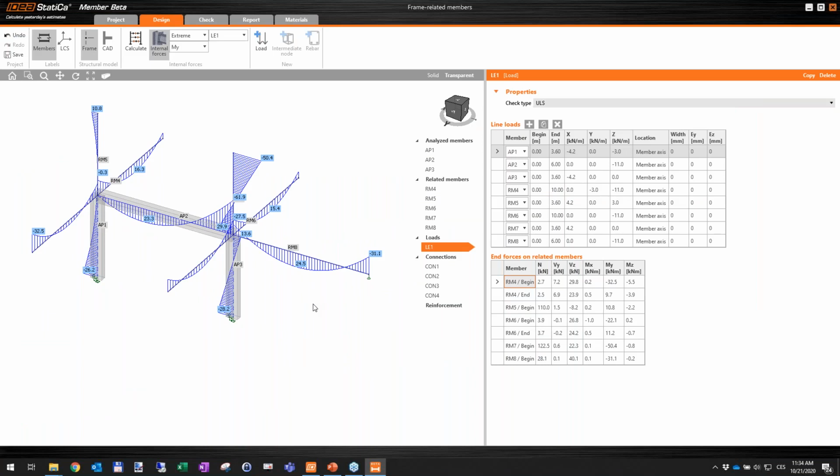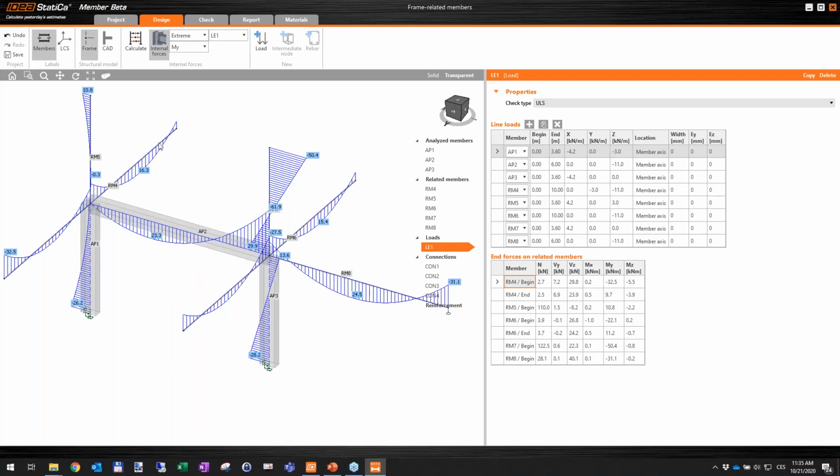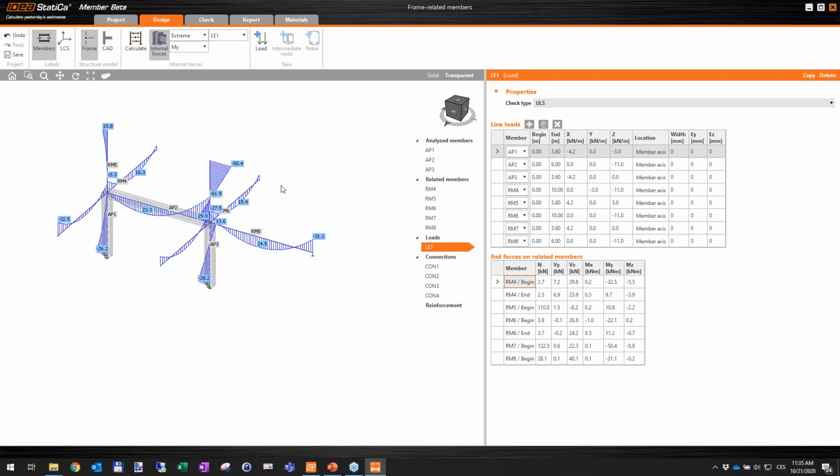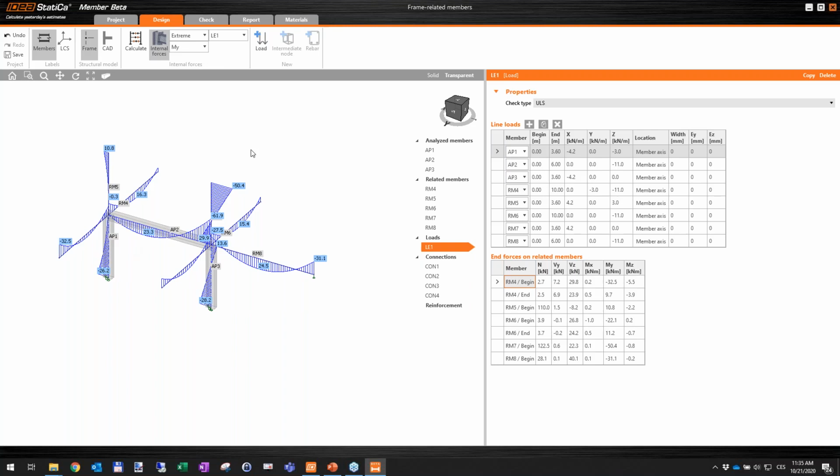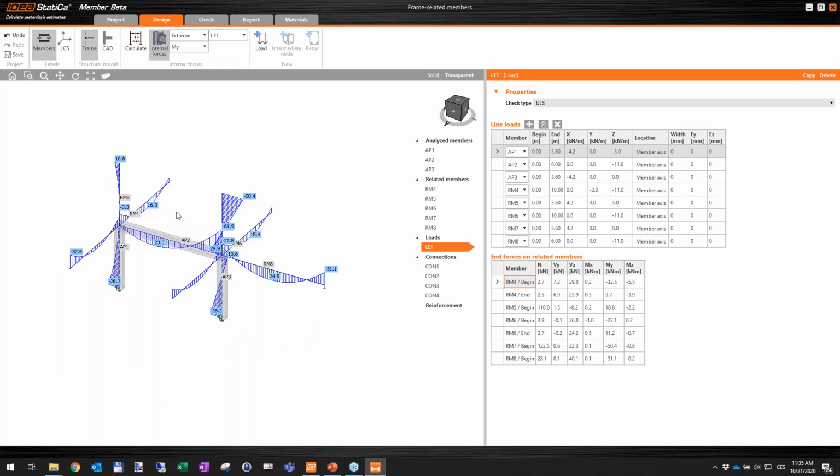Another explanation for related members is that such a model is already prepared for integrating the FEA software. So you will just choose the critical part in a FEA software, and it will import all loads or effects of the related members on the analyzed member. So the analysis becomes more realistic, and of course the code check could be safer and more economical.